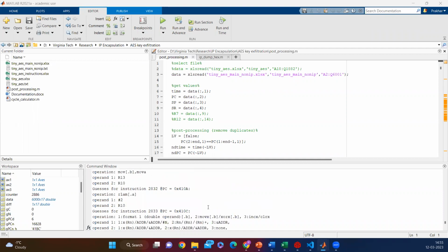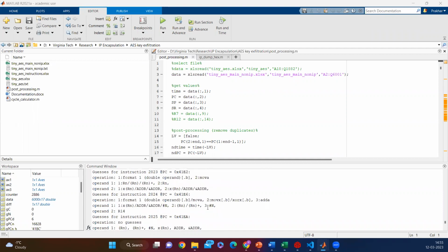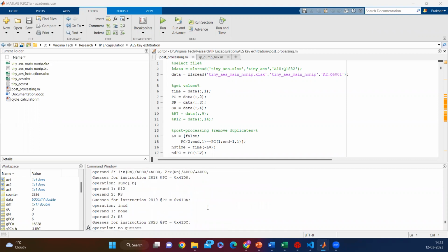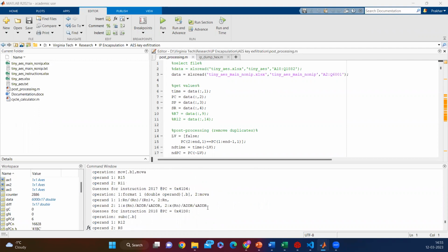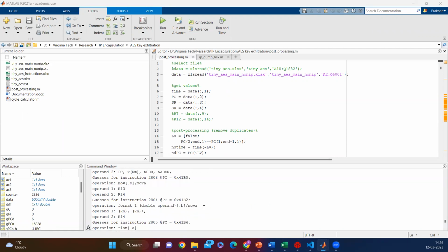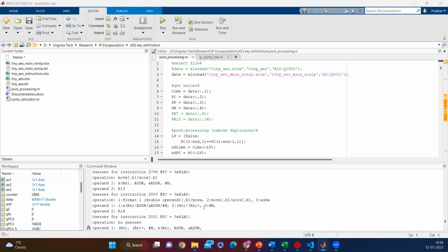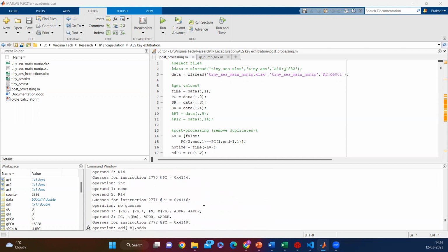Now, the kind of instructions that we're interested in to get the entire memory dump are memory to register operations, where data from some memory location is transferred to the actual register so that we can read it from the register file, and we can control the memory location that we provide in this instruction. So how do we find such instructions? Let me give you an example of one.